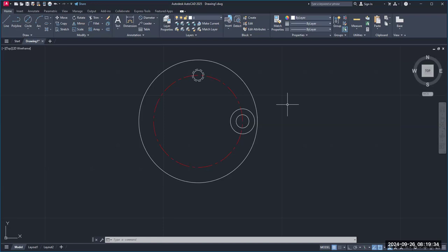You're providing a seat, a place for the screw to sit down. Okay, it's a rough surface. A screw is not going to properly seat itself if the surface is rough, like in the case of a metal casting that has a rough surface a lot of the time. All right, so you're going to provide a seat for that screw.